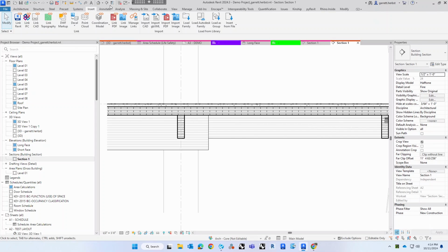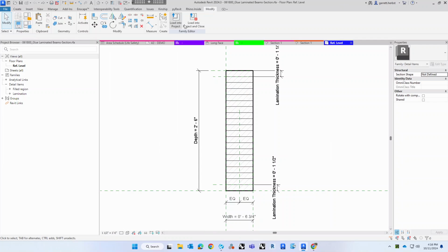And what Revit did, which again, I just don't understand why, but it's Autodesk, so whatever, is that within a project, to create, edit, and manipulate line work, you go into manage, additional settings, and then line styles. That's where you can go in and manipulate all the different line types.